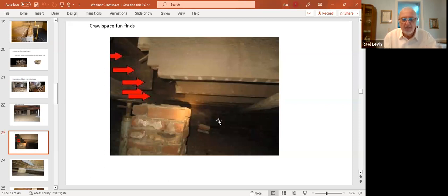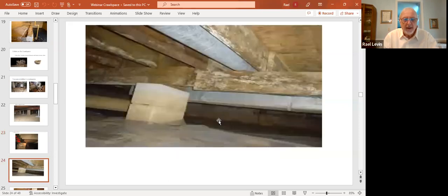So certainly this would have needed to be addressed and gone into the report. We can see here the mold that's on this one, and this was really low. This is like barely 18 inches. Got a 16, an 8-inch cap block here, plus another 2-3 inches, so 11, 12 inches. It was a challenge to get in, but we did have a vapor barrier down. However, there was still moisture getting in, as you can see by the mold that was in this particular situation.